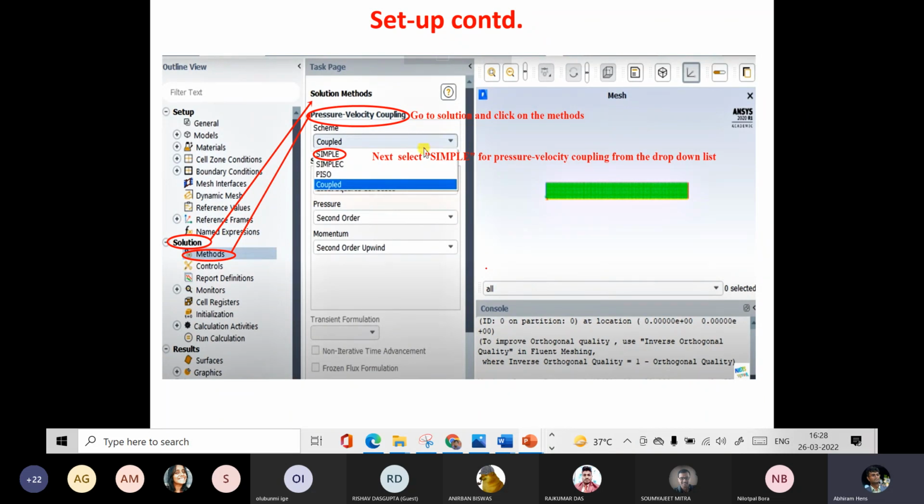So that I will discuss later, but you know that for this pressure velocity coupling, different varieties of algorithms are available. Okay, some of these algorithms are written here, like simple, simplex, piso. There are so many, there's a big list. So we will try to cover the simple algorithm, at least one algorithm I will try to give you at the end. So we have to select some algorithm. Now how to select them? I mean, how can you know which is going to work better? Because each of these algorithms has certain advantages and disadvantages.